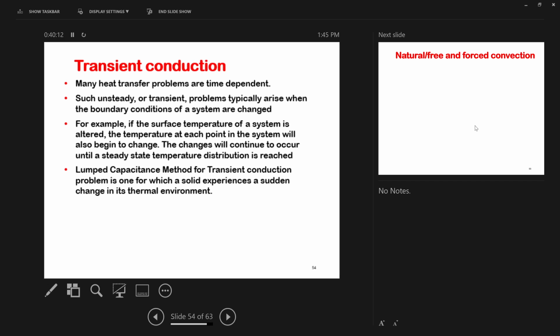If you go inside a little bit, you will have other temperatures that are still larger than Ts, but smaller, let's call it T2, than T1 and smaller than T infinity, which tells you that there will be a temperature gradient inside this solid ball. What mode of heat transfer does this remind you of? The temperature gradient inside of a solid ball. Conduction, right? Okay. But we also have heat transfer outside of the ball, right? What mode of heat transfer does this remind you of? Convection, goes to fluid.